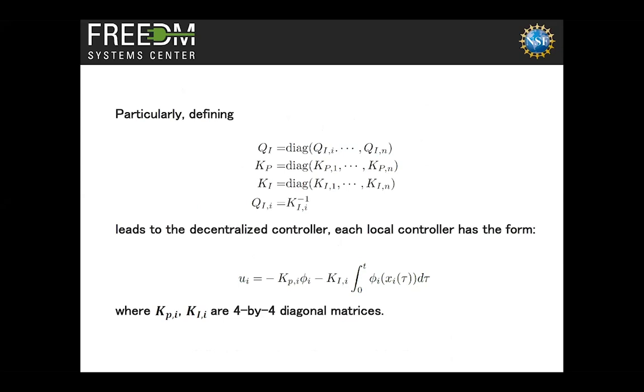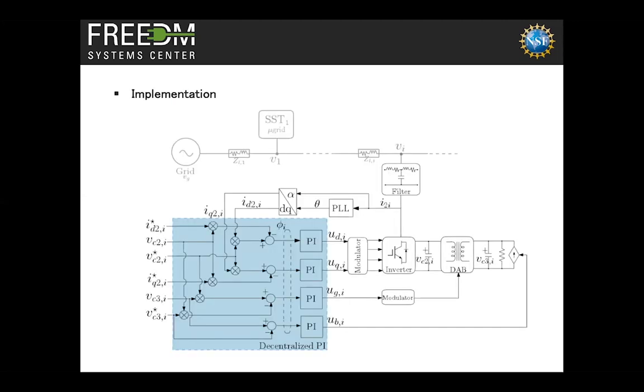And again, depending on operating conditions, depending on the set points, the star values, and the topologies that you have, it may be easy, it may not be easy. It depends completely on the system configuration. This is the implementation diagram, and I think it is interesting in the sense that it tells me that my system has bilinearity, but I'm getting rid of the bilinearity by making one of the outputs the star points essentially, which means that it's a constant. And that goes back to the incremental passivity idea, that I'm measuring everything with respect to the previous equilibrium.